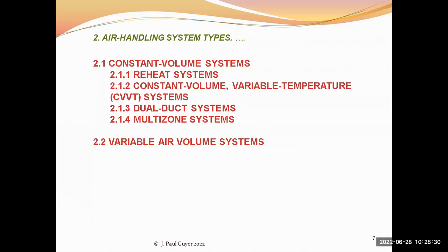And so it resets the temperature of the cooling water or the heating water. That is an approach in older buildings, older systems: constant volume, variable temperature systems, where you are varying the temperature of the chilled water and the hot water.